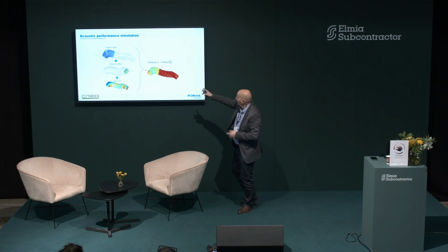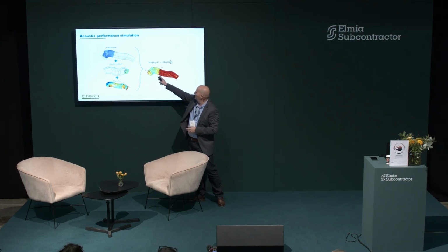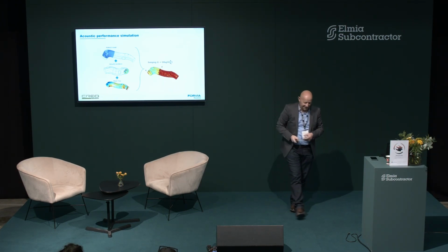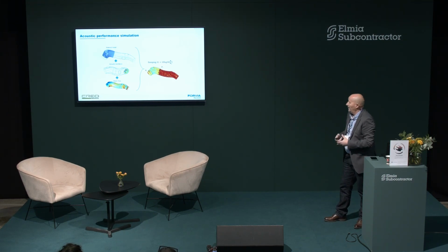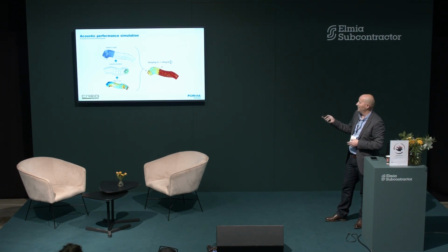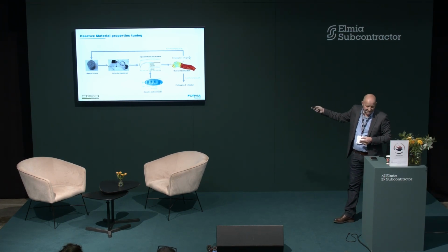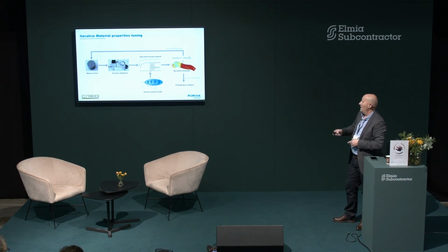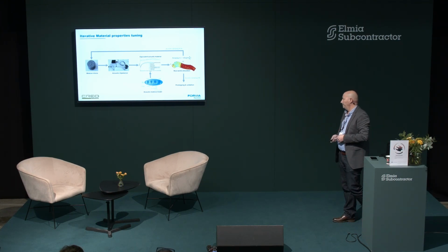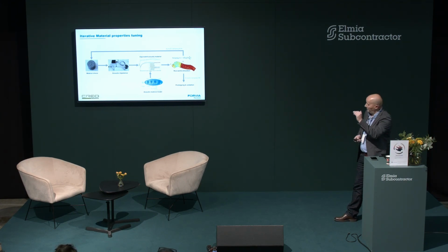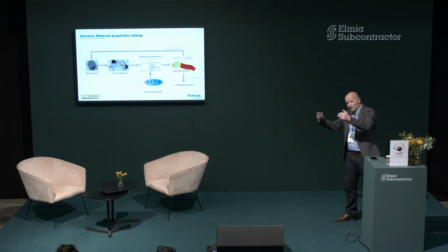This simulation gives you exactly what is happening in the tube in terms of acoustic level. And here, the important information is what is the absorption between this point and this point, the two positions of the treatment, and to be able to determine with the simulation at the design stage the performance of the solution. So you have the whole process that is established, and basically what is needed then is to iterate. In that case, we needed to iterate 2 times and ended up with some performance that was fulfilling the requirement, and then we could go to the next step.